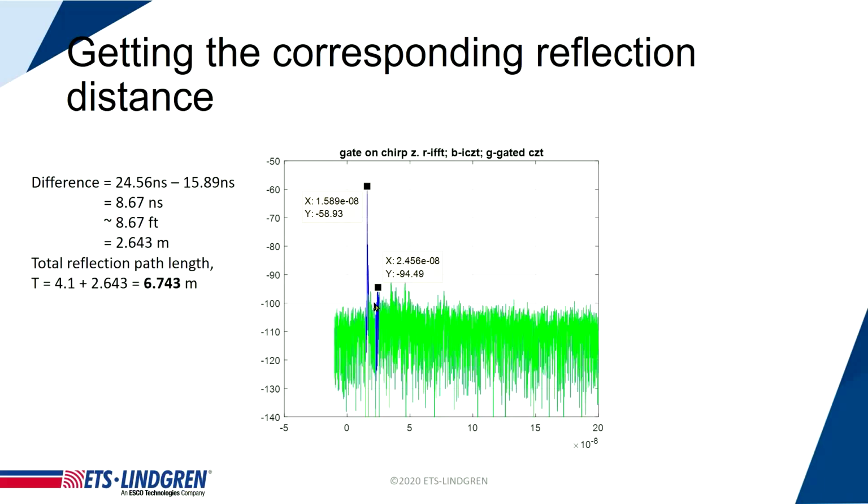If this is the one that is dominating, or this one would change the chamber and make it compliant, obviously this is the one we need to deal with. At the same time, you might not find that immediately. You can try several other places. In this case, most likely you're going to try the second one because this reflection looks pretty big. We delete that, and it really didn't make the chamber pass. It's actually this one.